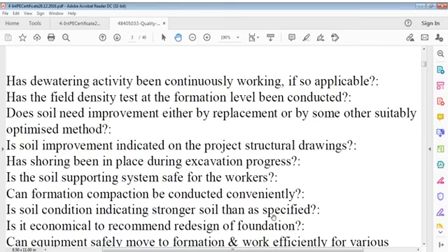So, in the absence of permeability, there is no way that water can flow on its own under pressure. It shall remain in the pores, and the soil will swell. So dewatering depends on that. In a well point system, water flow is very limited. It comes in very small quantity, but when you consider sand soils or other non-clay soils, for example rocks, when water comes in, it is a different type of flow. So we have to think and decide this.